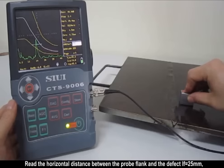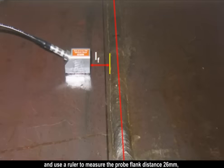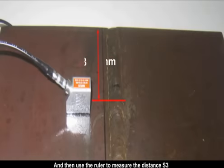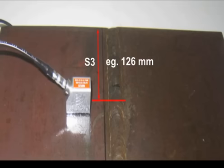Read the horizontal distance LF between the probe flank and the defect, which is 25 mm, and use the ruler to measure the probe flank distance, 26 mm. Then the distance between the defect and weld center is 26 minus 25, which is 1 mm. Then use the ruler to measure the distance S3 between the probe center and the test block left edge, for example, 126 mm.